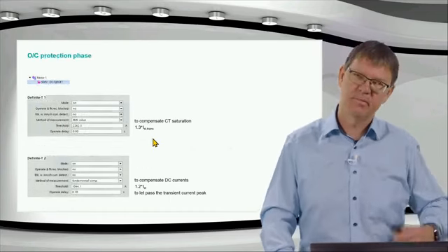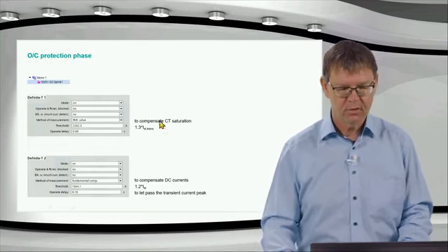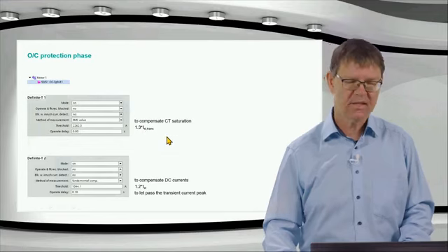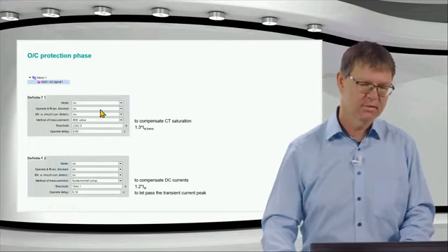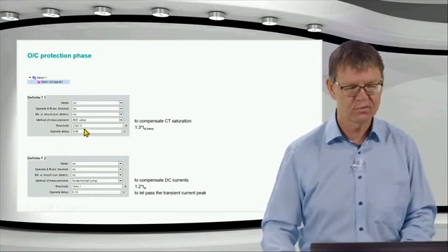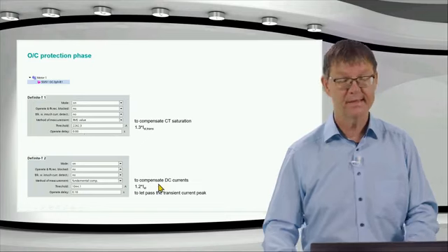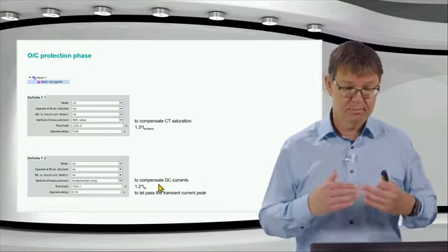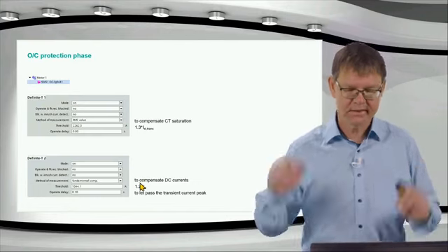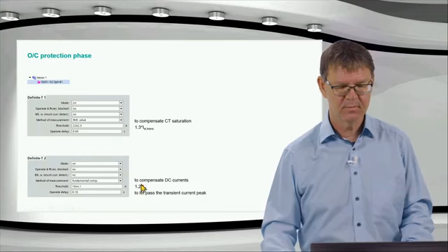Overcurrent protection, so this is a repetition of the first session we had here. Here I go to 1.3 times the maximum transient starting current. All values here are in primary values, so as not to confuse too much. I use an operator delay of 0, and I take a second stage with a certain margin above the static, long-term starting current, 20% of that.